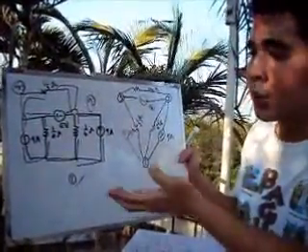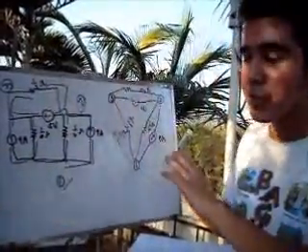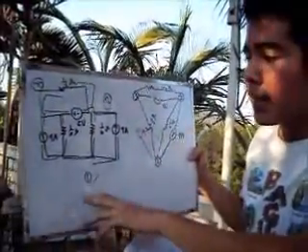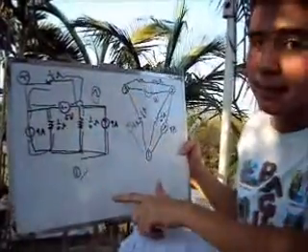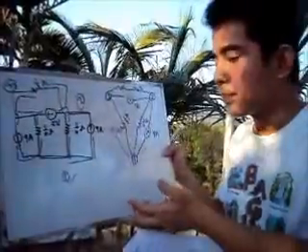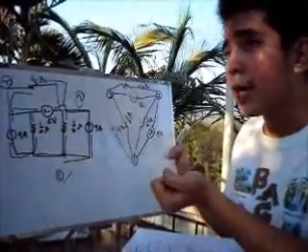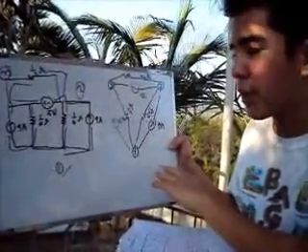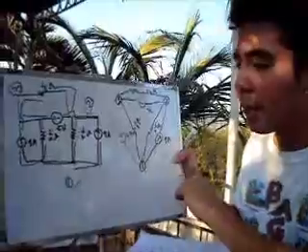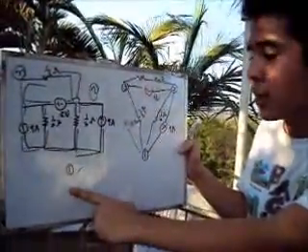For me, I prefer to redraw the circuit so that it will be easier for me to answer it. Here, I count the number of nodes: node 1, node 2, and node 3. Then after that, we're going to find the voltage reference. For easy solving, we're going to choose as our voltage reference the node with the more number of elements. So that is node 1.